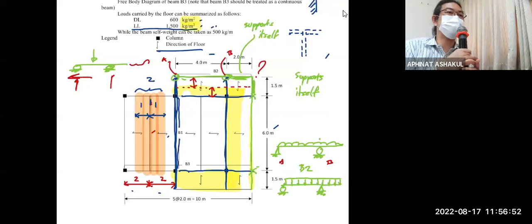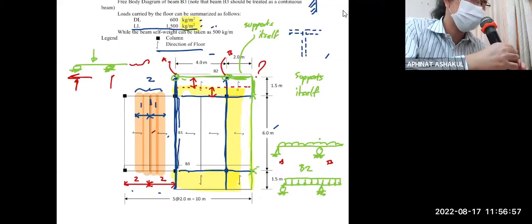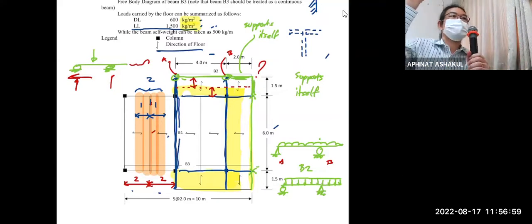Okay, so that means we can do a little calculation, right? Now, some students will forget this. I used to forget this because one time I had done so much steel structure that I forgot the weight of the beam. Because in steel, the weight of the beam can be neglected. But in concrete, no. Concrete beams are heavy.